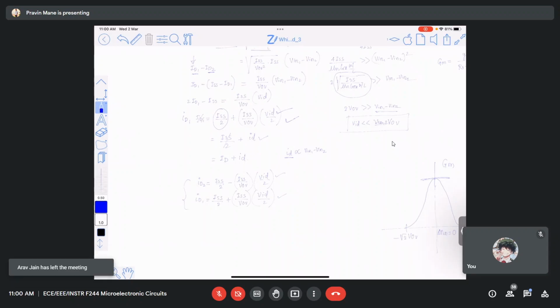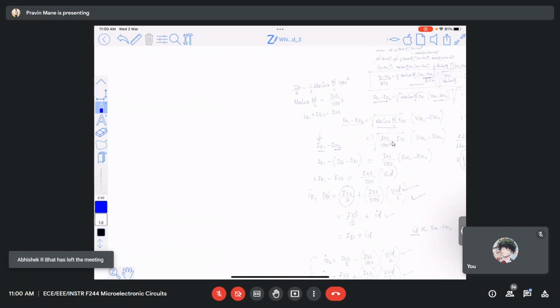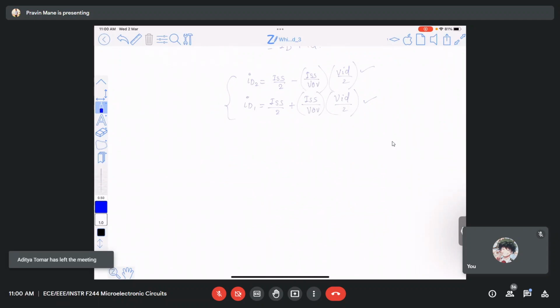One question. Does the formula that gain is equal to negative of resistance at output divided by resistance seen through source hold for every single configuration? Yeah, minus, but I said the sign will depend on the configuration. If it is a common source amplifier, it is minus. Otherwise, it is plus. So it is applicable in all cases provided that RO is neglected. Right. If RO comes into the picture, then the formula is complicated. Then we'll have to draw the model and everything, right? Draw the model or you can remember it.